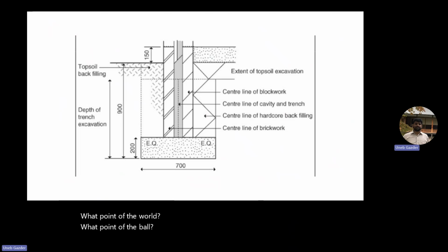Inside, outside, center, center. Okay. If your footing is under the walls, like a trench footing or a strip footing, we'll take it to the center line. Okay, same thing if your wall is one unit.